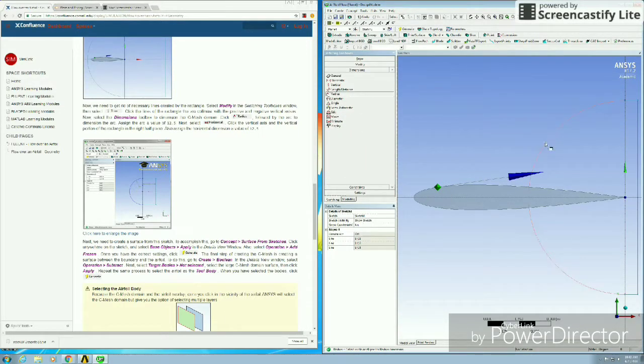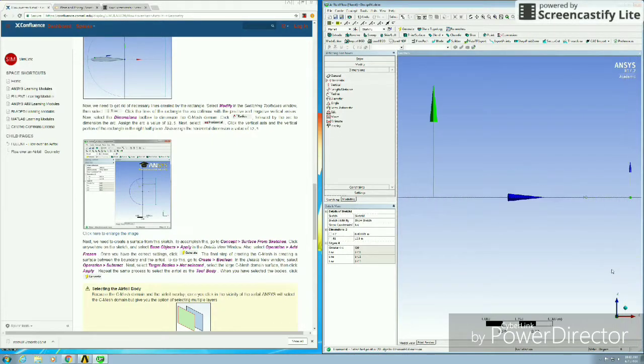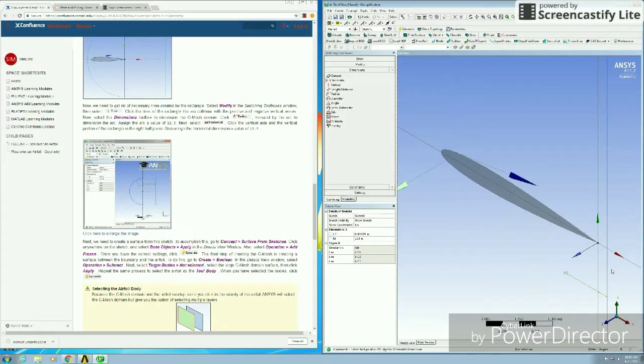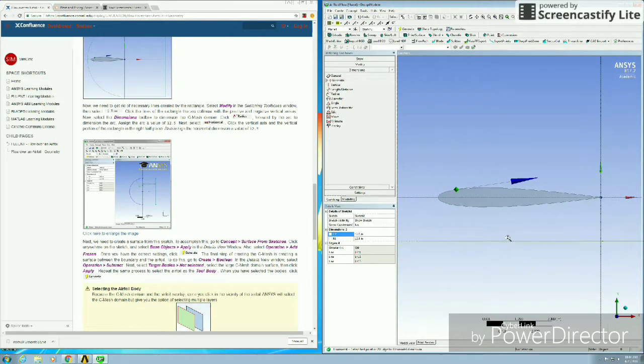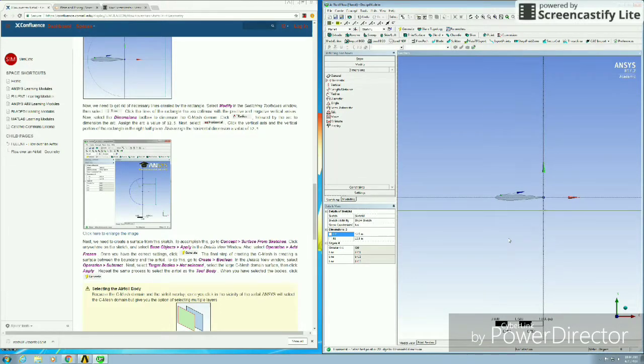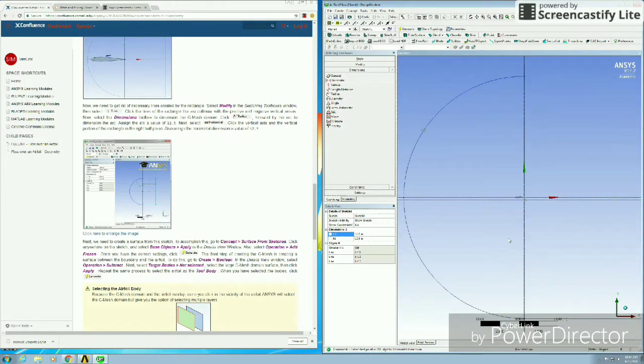Okay, cool. Now we're going to dimension the radius we just made, so just go to radius, and then you're just going to type in 12.5, and then go hit horizontal. You're going to click on the vertical axis and the y-axis that we just made, and also go ahead and type in 12.5. And if this happens to you, just go ahead and click on the face, the face that's facing the wall. Okay, cool. So now we're going to go ahead and type in 12.5. I didn't do that yet. Okay, and then you can go ahead and zoom out and see the large geometry you just created. It's kind of outside of the scope.